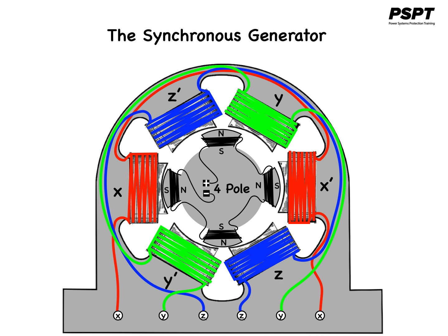They are wound alternately, creating a north and south pole on each of the protuberances. It is the flux in the air gap that we are concerned with, so I will remove the innermost designation. Not that it's not there, it's just that we want to concentrate on the flux that is in the air gap.